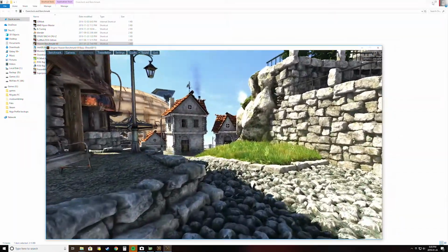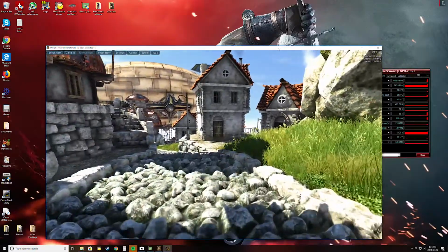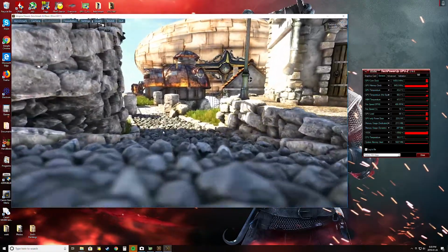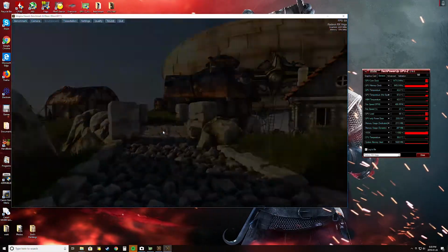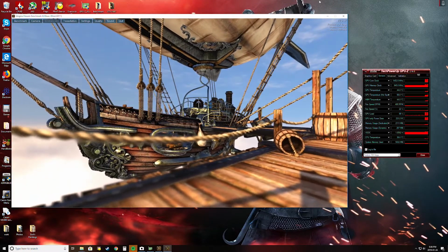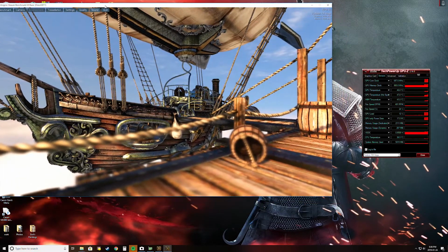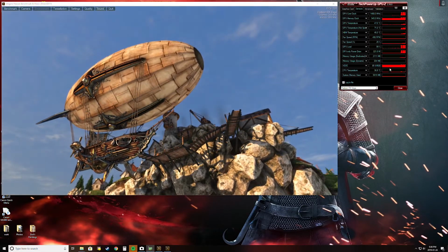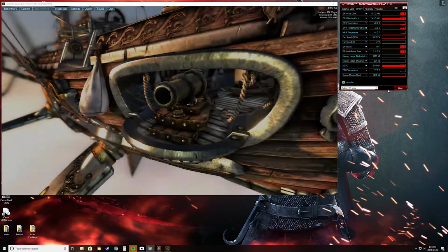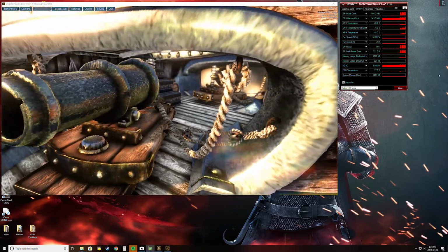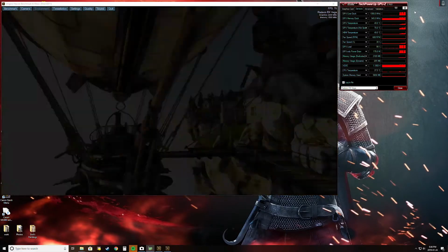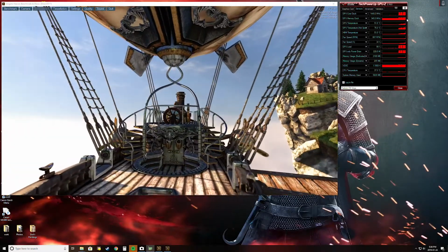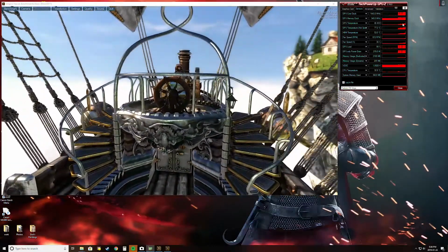Sound. So, all right. So we've got our GPU-Z running, and now we have our Heaven benchmark. And the reason I didn't click full screen and I chose a resolution that's less than what I'm running my default at is so that I can see the entire screen, my whole monitor, so I can still see the GPU-Z application. And what we can see here is that it's running at 1460 megahertz roughly, and the memory's running at 945 megahertz. And our temperatures are here as well.